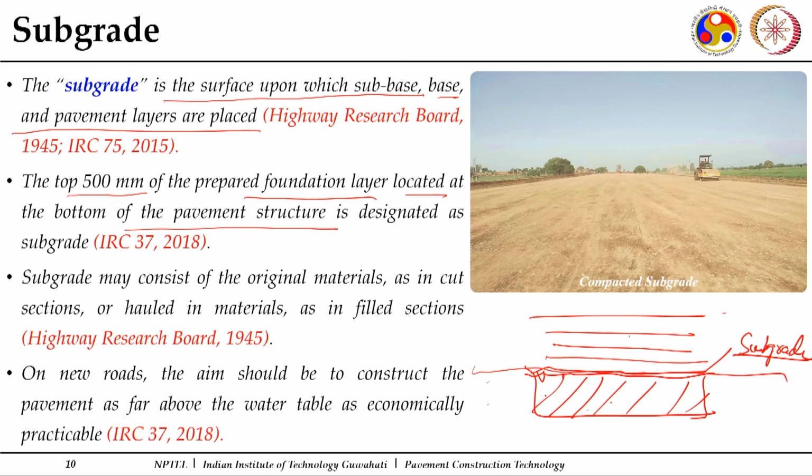If this existing soil is approved, then you can use it, or you have to bring borrow material, or you have to treat and stabilize it, and then reconstruct it in different layers. Because if you compact only the top, you don't know what the soil is like at, say, a depth of 20 centimeter.